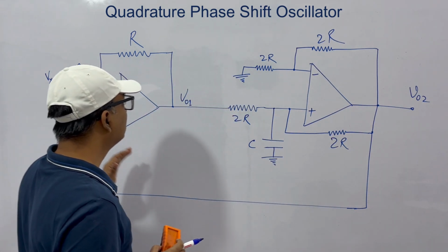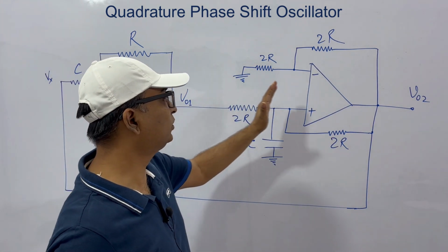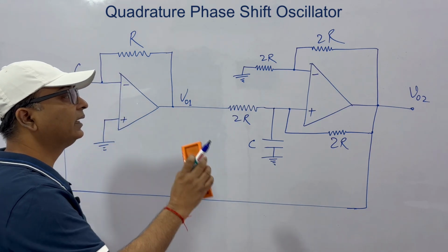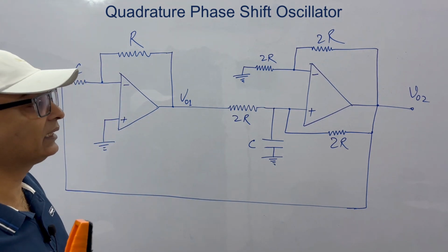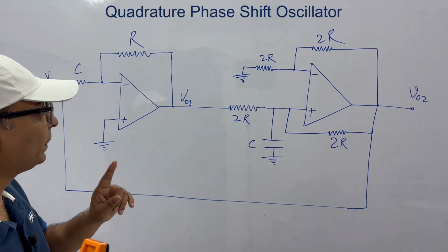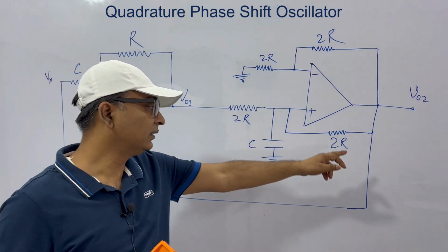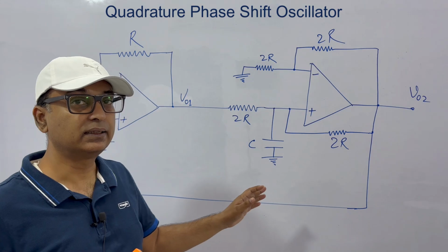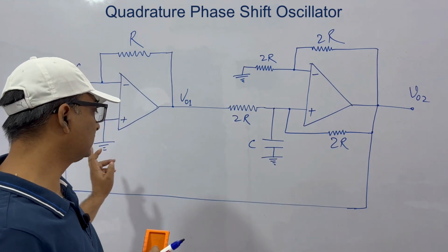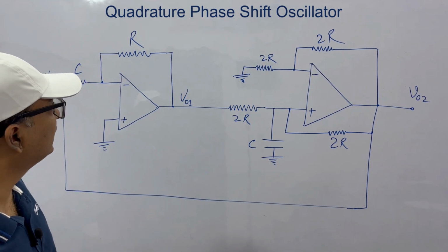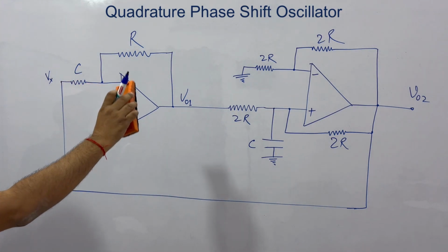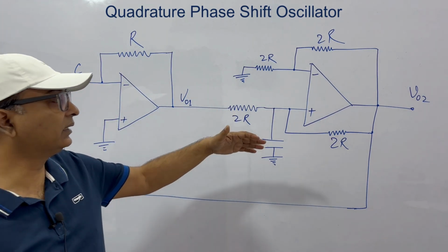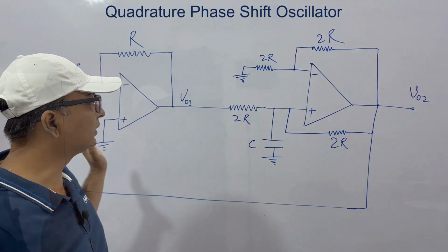So a signal crossing through these two integrators has no phase shift. That is, the phase shift is 0. First thing. Second, the feedback network is a short circuit. That is unity gain. That is what is achieved by having a short circuit. That is beta equal to minus 1. And these are CR, and these all are for stabilization and biasing and all.